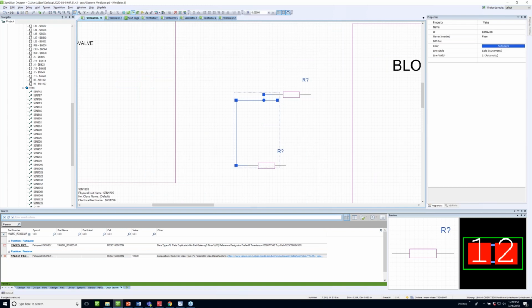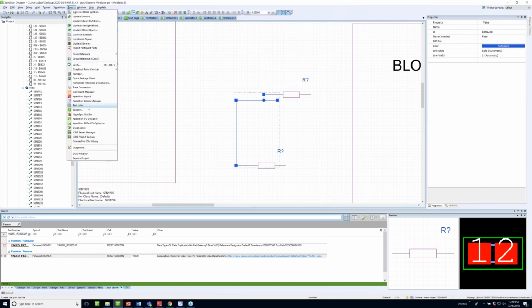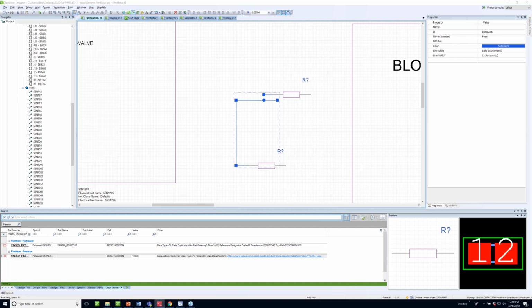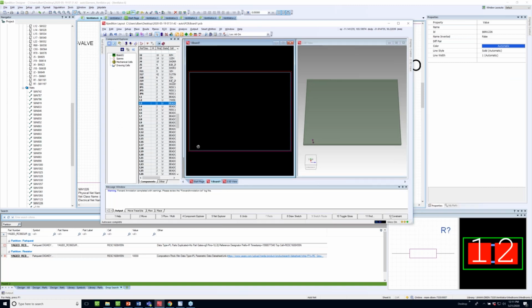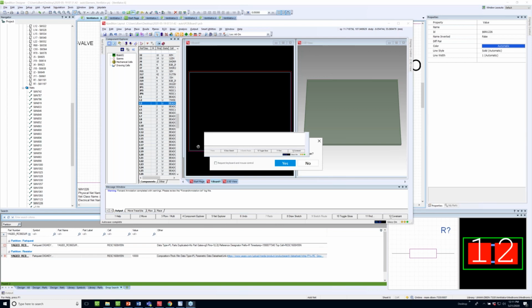Once that net is complete, what you can do is create a net list from the tools package. That will give you a representation that you can carry over to a blank circuit board where the parts will be ready to place. I'll move over to Gary to show you how those parts are placed and how the initial MCAD ECAD setup will start. So Gary, I'm going to share the screen with you for a second here. Okay.